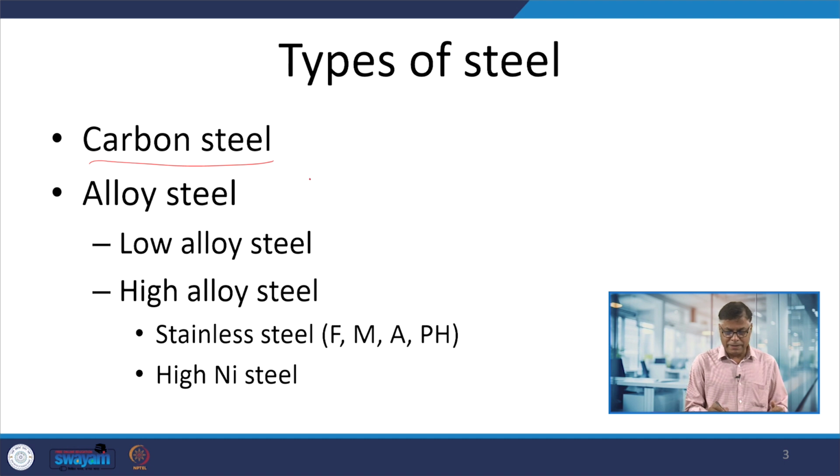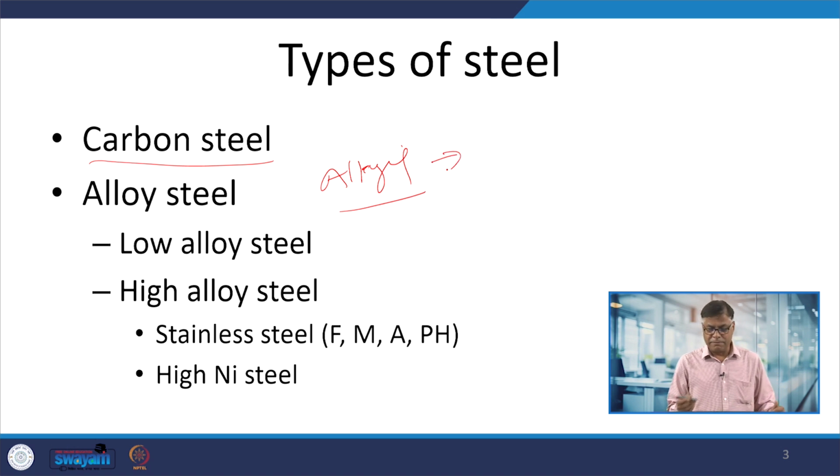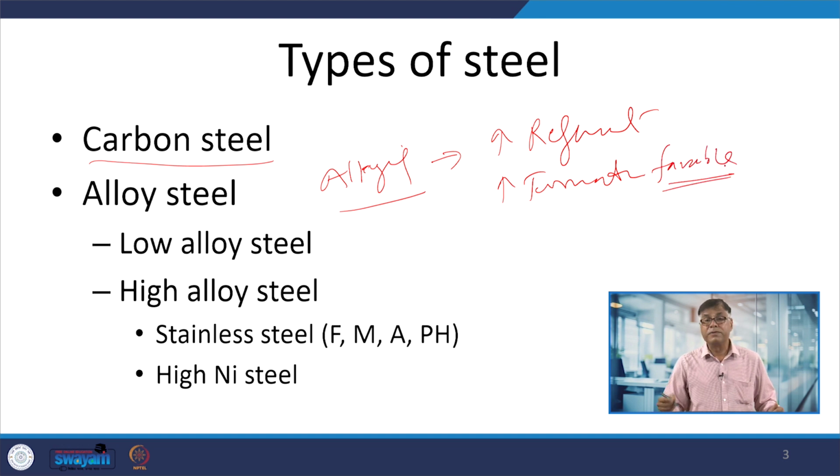So, what has been done is the controlled alloying of the plain carbon steel, which helps to increase grain refinement, or the formation of certain favorable constituents, favorable phases, in such a way that you get the higher strength without much compromising the toughness and ductility.